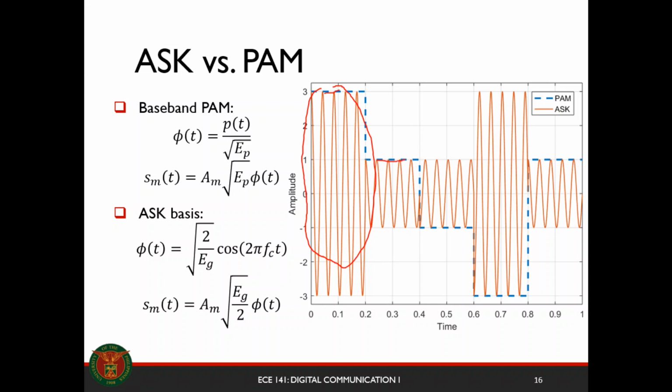So it's kind of like amplitude modulation, if you think about it. So the symbol is impressed on the amplitude of your carrier. Notice that in this area right here, there's some form of disconnect between the two symbols. Also here, it's not seen as much, but there's a disconnect. And this is actually a bad thing, but we'll get to that later.